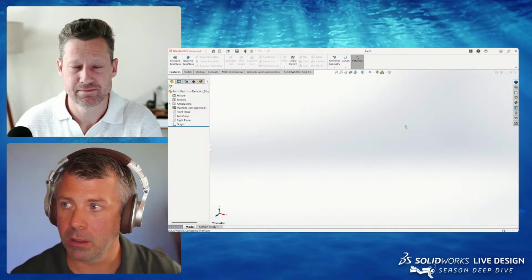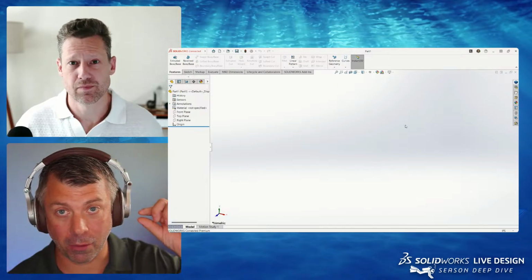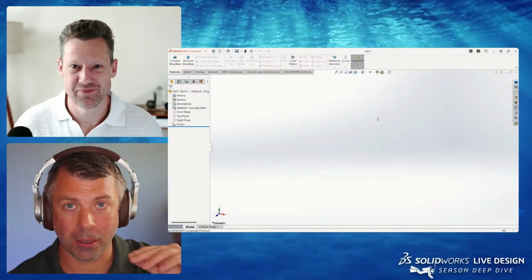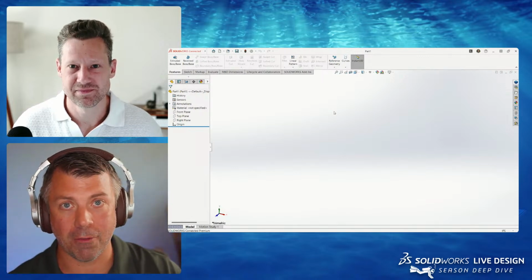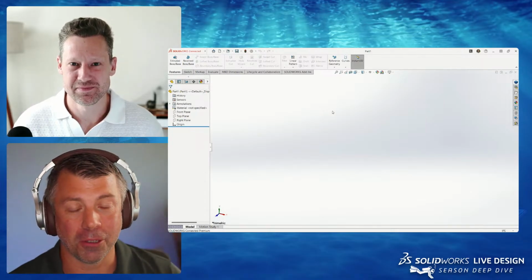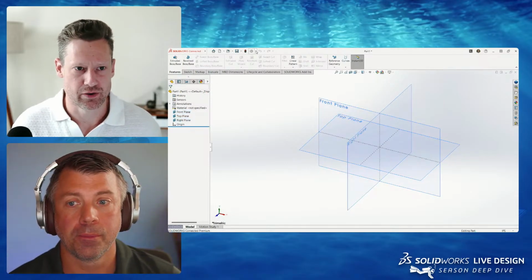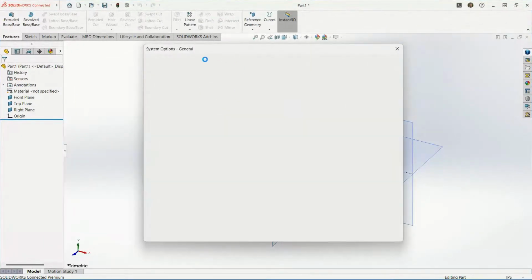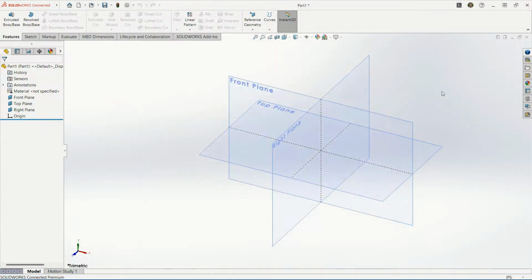And then I was at a user group meeting and someone showed that they had the weldments feature stored into a template, and they had a start part, and I thought, oh, you can save other things to a template. Of course you can. That makes sense. It's brilliant. That's awesome. And each one of these selections, if you're going to options, doing document properties, changing your units to 2 decimal places, all this sort of stuff, that's a lot of setup that you're missing out on.